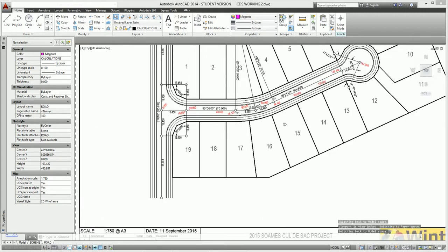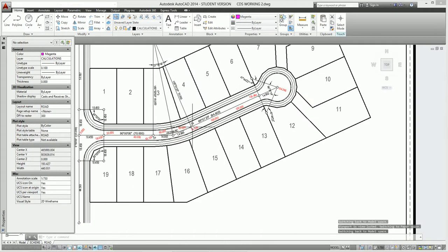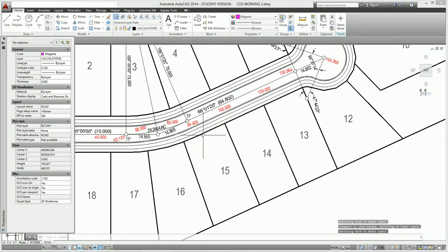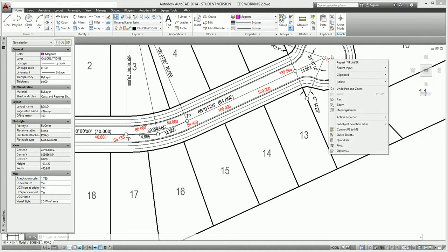So then it remains just to add on this length from here through to here, and that is obviously the 84.802 minus 14.865, and we calculate that out. I haven't got that exactly to hand at this point, and we add that on to the 84.429, which gives us 154.366 as the chainage distance at the end of the right-of-way there. So that's that chainage point there at the centre of the right-of-way. So there are our chainage points.